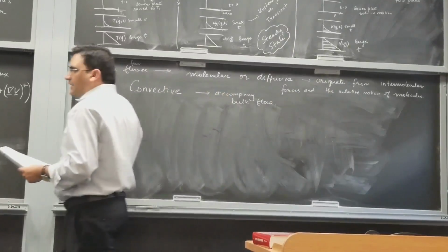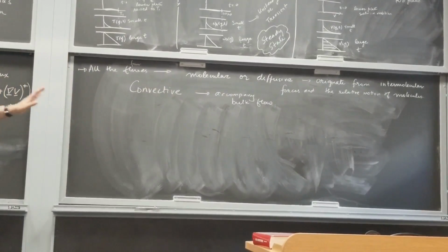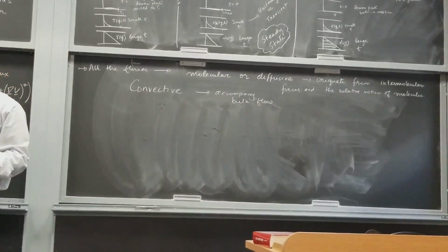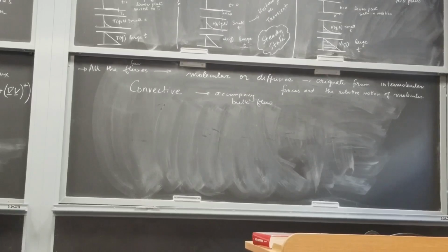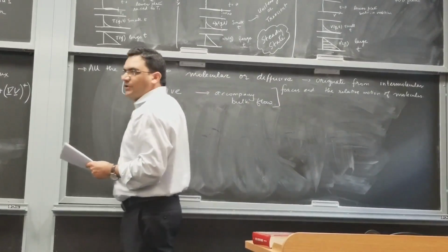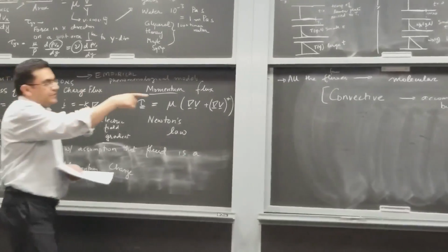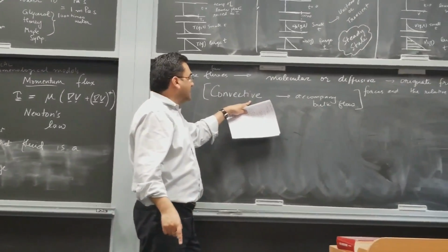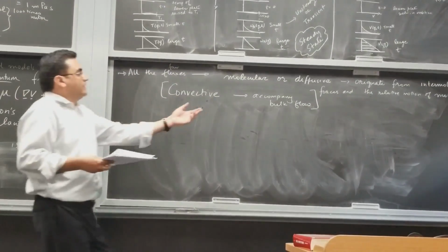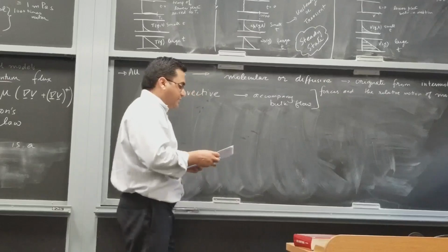Again, when you drink your coffee with creamer, if you add the creamer and then allow diffusion to do the work, it will take more time for it to mix than for the coffee to cool down. Whereas what we all recognize already is that we have to use bulk flow. So we are relying on convective mixing. Because heat transfer and mass transfer are typically much faster when you have flow, in many practical situations you need to account for both. And to calculate any convective transport of heat or mass, we also have to use fluid mechanics, because that will tell you how fast the fluid is moving. Once you know that, we can calculate how much heat or mass it's going to bring with it.